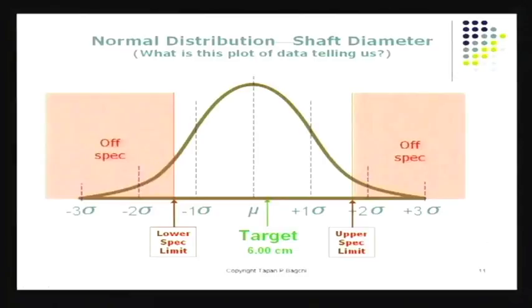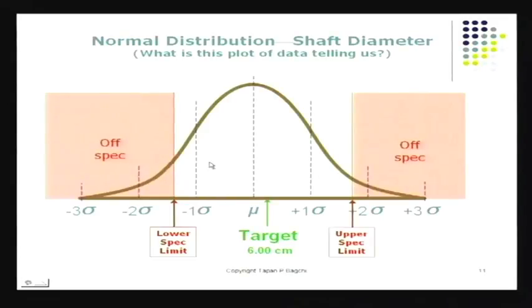The machining process itself does not change the cost of production from item to item to item. It does more or less the same thing as the different pieces are floating through. But if I end up with a lot of parts which turn out in the red area, either off spec because it's too tight, or too loose, therefore again off spec, if these are a large share of our production, we've lost that much money because we cannot sell these parts, we cannot use those parts. The only parts that we can use are those that are within specification. So what we would like to do is, first of all, have the output average exactly on target, and not to the left nor to the right.